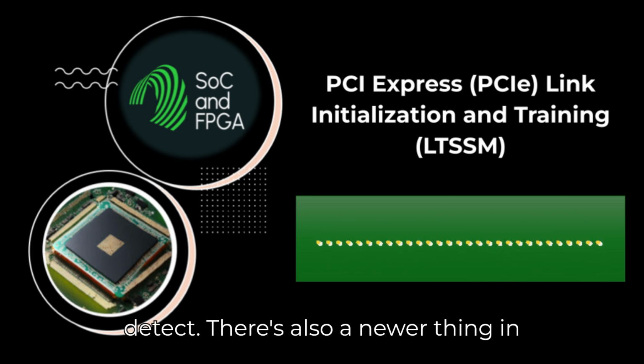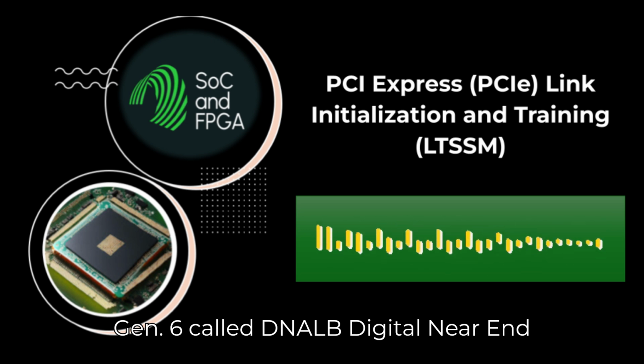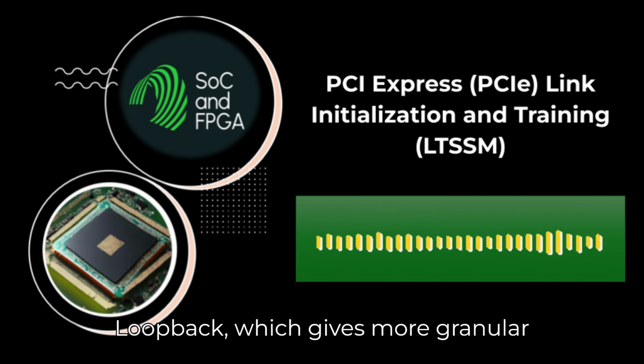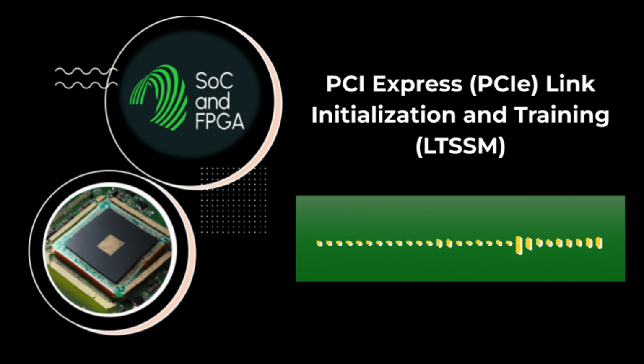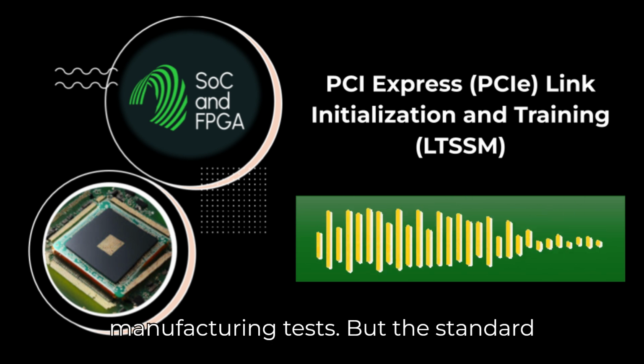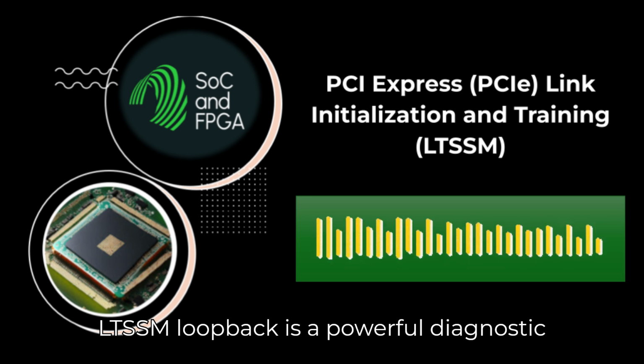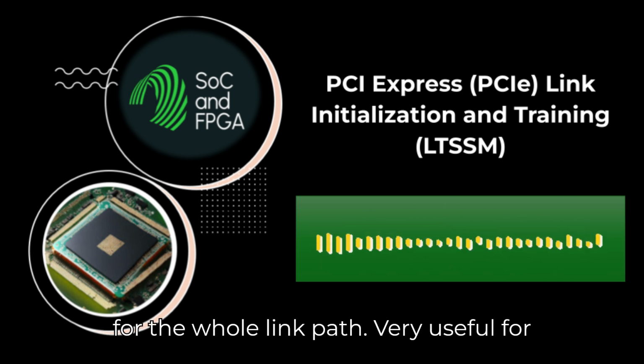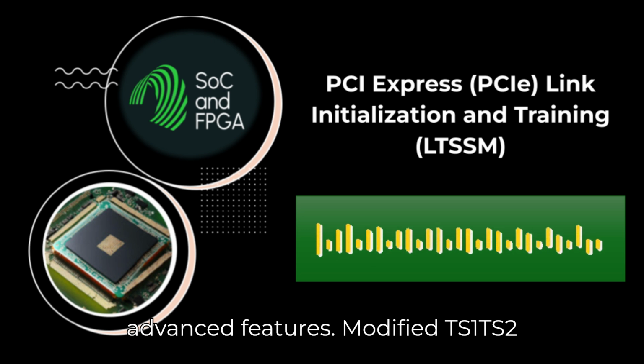There's also a newer thing in Gen 6 called DNALB, Digital Near-End Loopback, which gives more granular control over internal loopback paths within the PHY itself, useful for manufacturing tests. But the standard LTSSM loopback is a powerful diagnostic for the whole link path. Very useful for debugging. Okay, let's shift to the really advanced features.